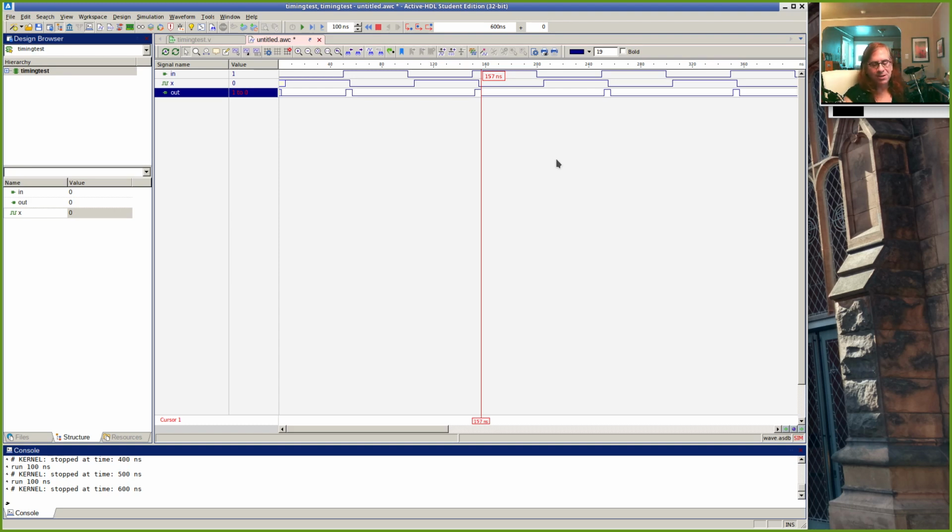So that's why we talk about clocked circuits. That's why we talk about state machines that we've been talking about for the past few weeks, because we don't want to just take inputs and have them drive outputs and do whatever those outputs tell us. We would have a clock ticking, and the clock would tick after these glitches have gone away. So we'd tick the clock right here, and we'd say, oh, we've got a 0, and we'd tick the clock here, and we say, oh, we got a 0, and we never see those little noises.